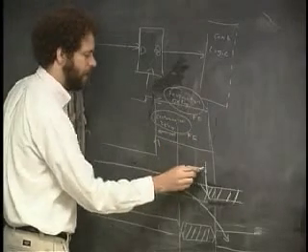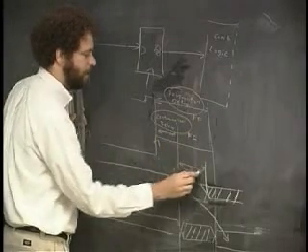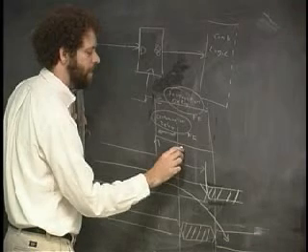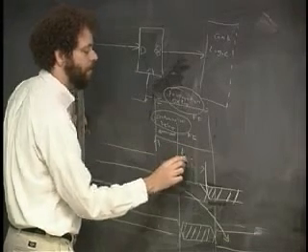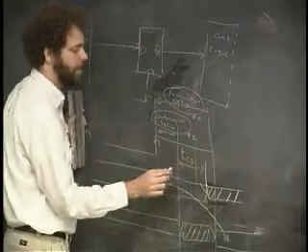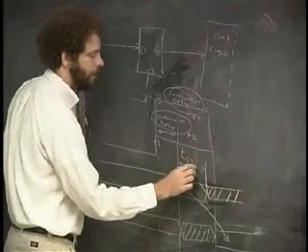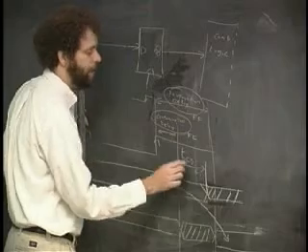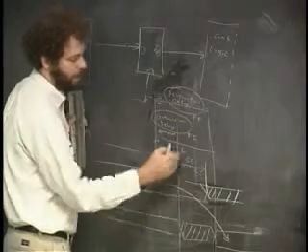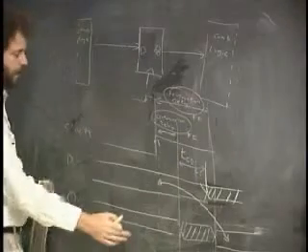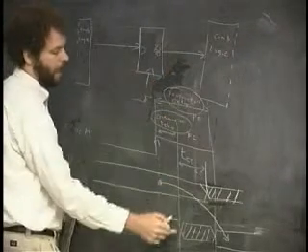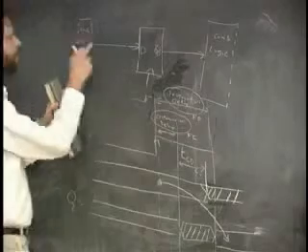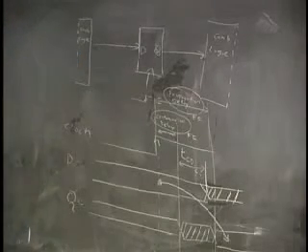There's another time here, which is, and I'm just going to write this now with the actual symbols that we're going to use, TCD, for time contamination delay of the combinational logic. TCD of CL, between when the input to the combinational logic is contaminated, which is this thing here, and the output to the combinational logic begins to be contaminated as well.